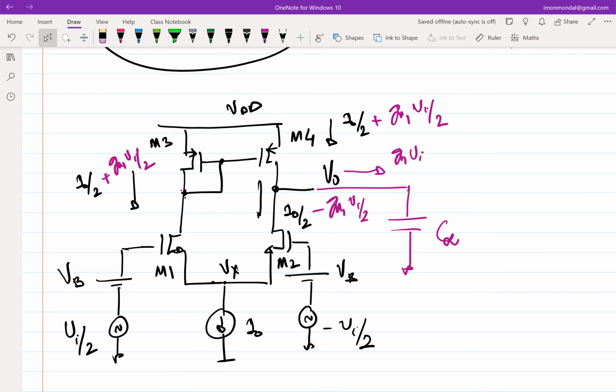So the incremental current that is flowing in this part is independent of what is there on the load side. But you are getting an additional incremental current because you have this current mirror, and this mirroring is providing that extra current. So that essentially is doubling the short circuit current. So you are still getting that extra gain, extra short circuit current gain, even though you are taking the output from only one end. That is one of the effects of adding a current mirror.